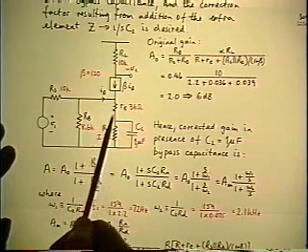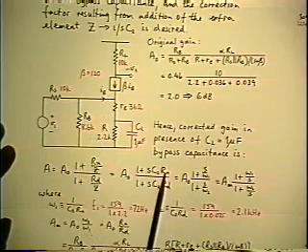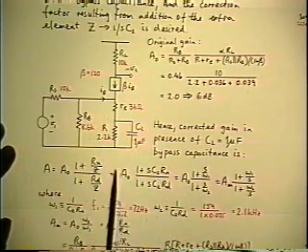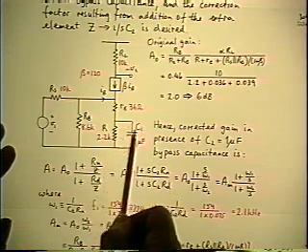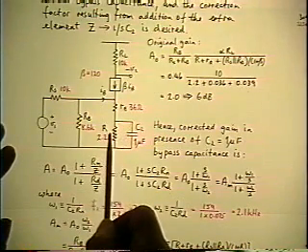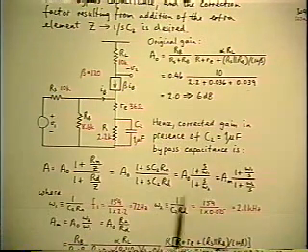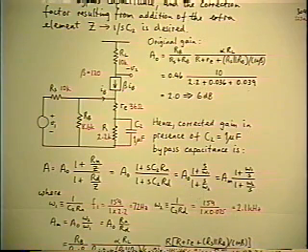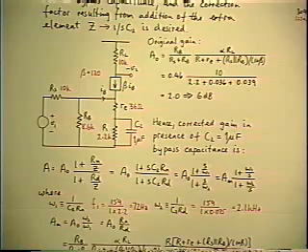It's the pole. And so it's a common error to guess that the bottom end of the frequency response is determined by the C2R time constant. It isn't. It's the wrong corner. I'm sure you know all that because you're experienced with these things, but a lot of people, students especially, don't realize that for maybe quite some time.